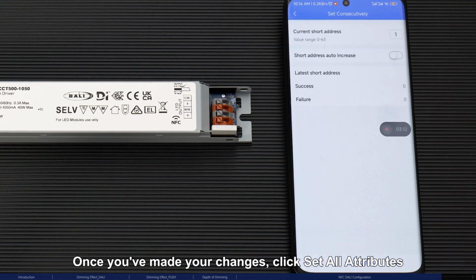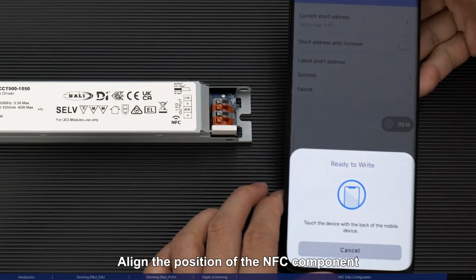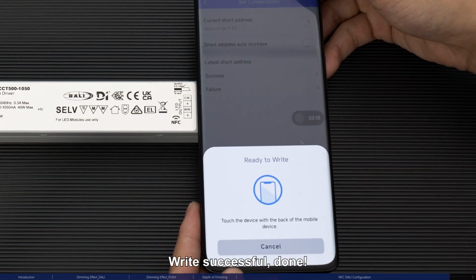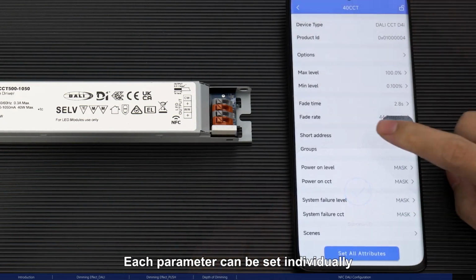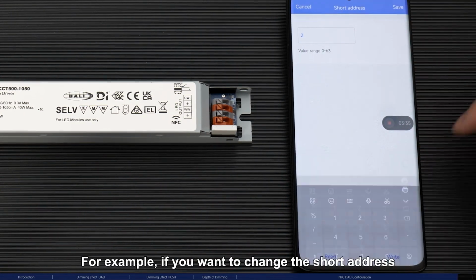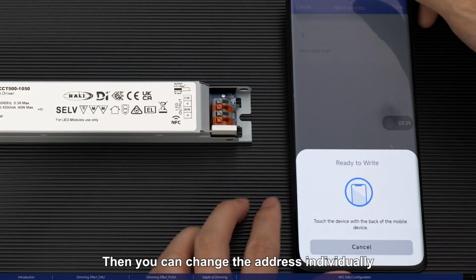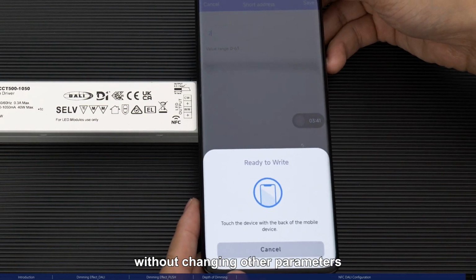Once you've made your changes, click Set All Attributes. Align the position of the NFC component. Write configuration. Write successful, done. Each parameter can be set individually. For example, if you want to change the short address. Once you have made the changes, click on Write below. Then you can change the address individually without changing other parameters.